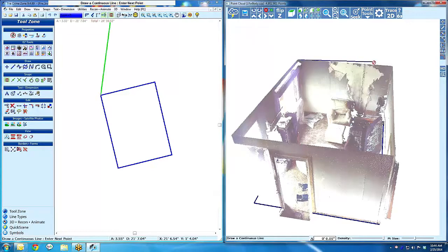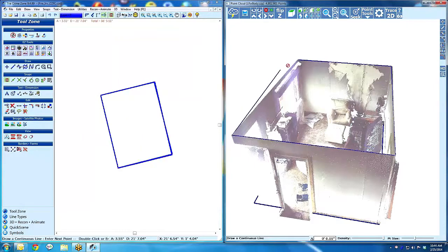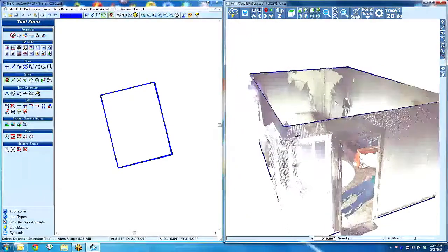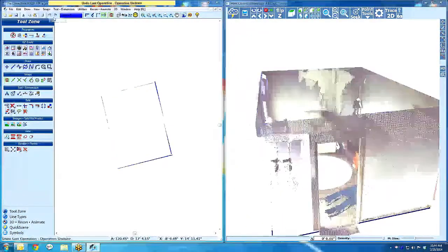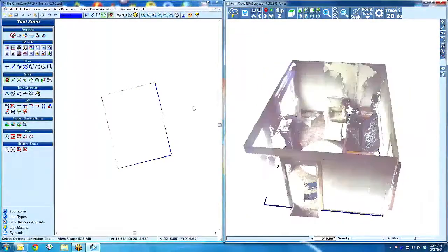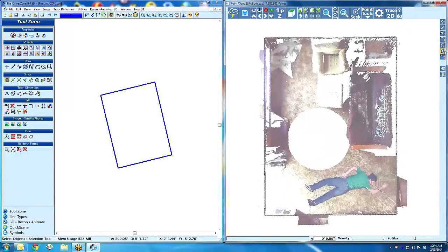I can go, I'll start right on the corner here, maybe here, there. And see, we can just go along and draw three-dimensionally, but we've come up with some tutorials and tricks to make this a little bit faster. So we like to do the 2D down, and then we can outline things like our furniture very quickly and then just put symbols in place.